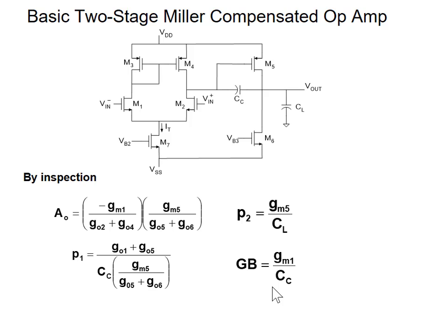Okay. So a lot of people like to talk about phase margin. I'll talk about phase margin also after I talk about poles. I'll probably do it for 2 reasons. Number 1, I don't want you to be non-conversant with other people that are in the industry. But I'm not a big advocate of phase margin. Why? Because you can build systems that have phase margin that looks good, and they're lousy. You don't build systems that have poles that look good and are lousy. The good news is, usually we're looking at second order systems. With second order systems, we will look at exactly what the relationship is between phase margin and pole locations. So then you have your choice.